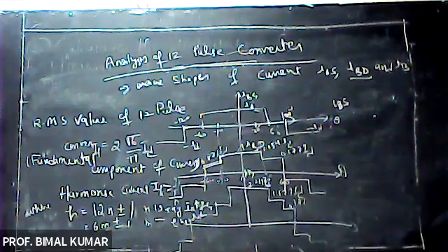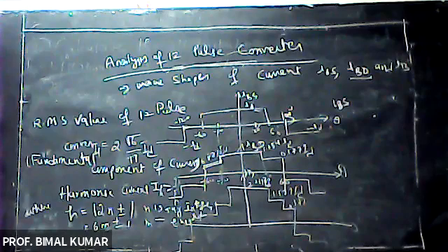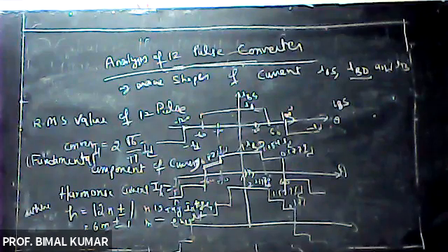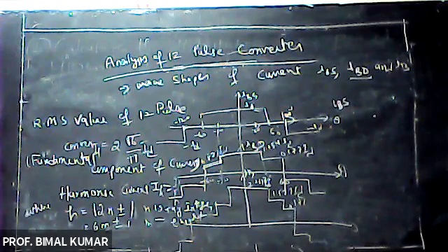So in comparing with the harmonic current of 6 pulse converter, it is obvious that the 5th and 7th harmonics flowing in the two transformers cancel each other, right?